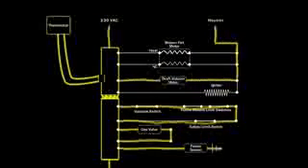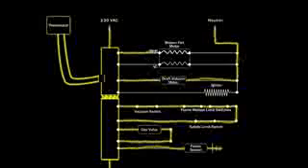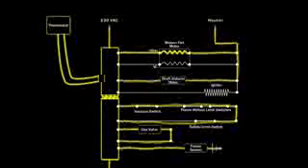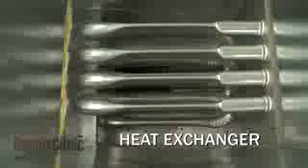If the furnace is located in a closet or another cramped area, the limited available air may prevent the combustion process from working properly. Closet doors will need to be louvered or space left at the bottom of the door to ensure proper airflow. Once the combustion process is complete, the control board will send 120 volts to the circulation blower fan motor. The blower fan draws air through the return vent, blows it past the heat exchanger, and forces it through the